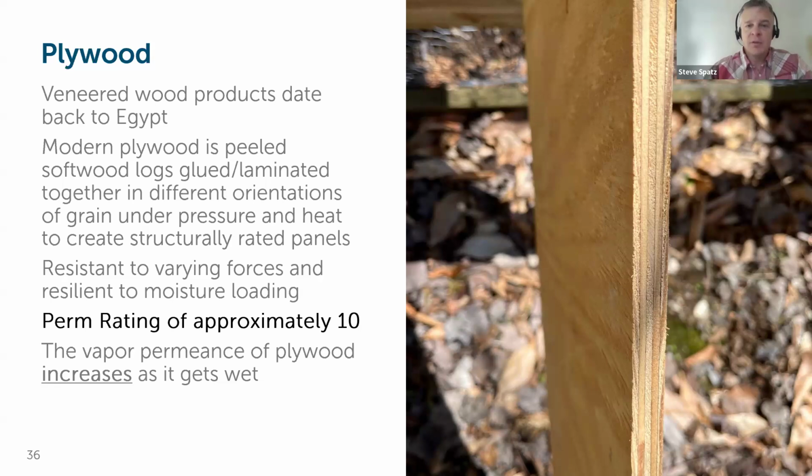So builders who are looking to build very completely vapor open assemblies, entire performing building assemblies, have been using diagonally oriented 1x dimensional sheathing as a structural sheathing layer, which again, that wood being in its raw form is very vapor open. Any moisture vapor that would see from inside the building is going to, if it loads into that wood, that 1x material, it will dissipate easily over time,